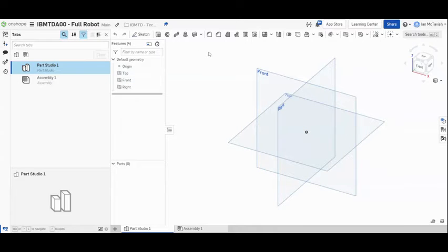I'm going to be going over this fairly fast. So with the video, you can refer to it, and I will try to explain what I'm doing as I do it. So that will hopefully help. A couple things. You'll notice that we have our three planes, our top plane, our front plane, and our right plane, and our view cube over here where we can click part of the view cube to rotate our view. So we're good. What we're going to do is start with the top plane.